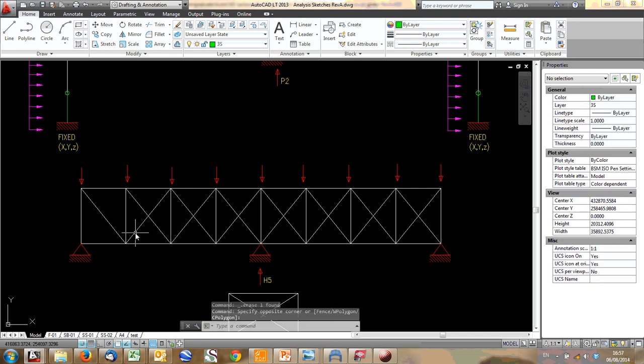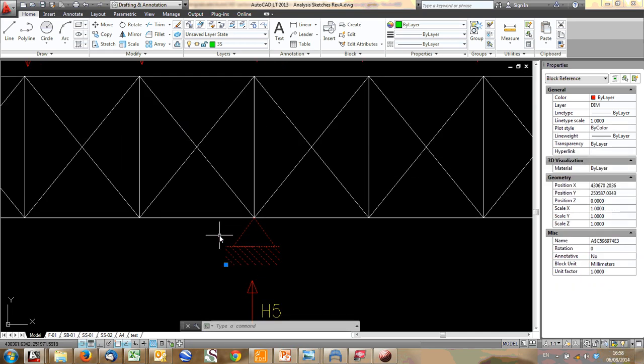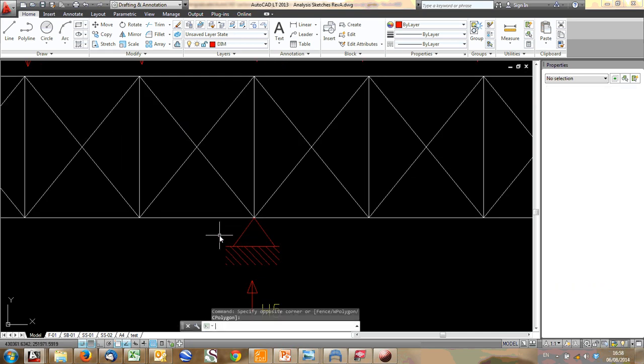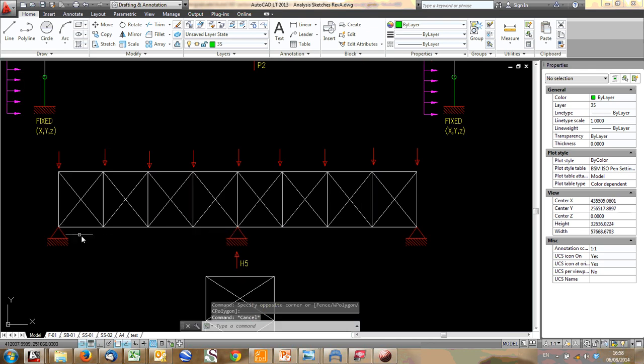These are tension members, so let me show you why I'm doing it. When this goes into bending, obviously this bottom will go into tension and might go into compression over here. This will go into tension and then compression, tension, and then compression, tension. These internals will go into a series of tension and compression.